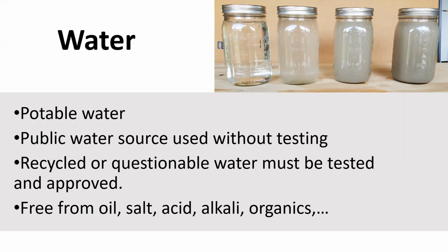You don't want oils, salts, acids, alkalis, organics, anything that's going to change the strength, the workability of your concrete, if you want something that is going to be pretty low maintenance. So you have to be careful when you talk about recycled water, and you have to have a system in place.